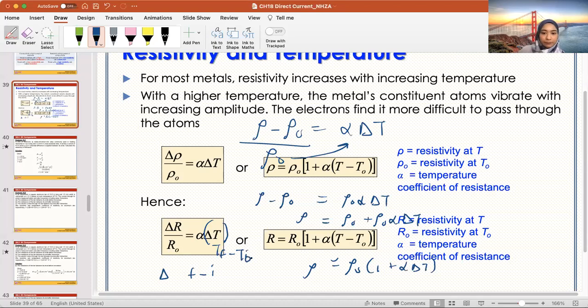Same. Okay. So resistivity is rho, R is resistance. So that's different. So you have to differentiate between the two. So resistivity is dependent on, we know this equation, R equals, resistance is dependent on resistivity and is proportional to length over A. This guy is a constant, but with temperature, it can increase in value. But usually we will be given the value of resistivity at 27 degrees Celsius. It's okay, we will do an example.